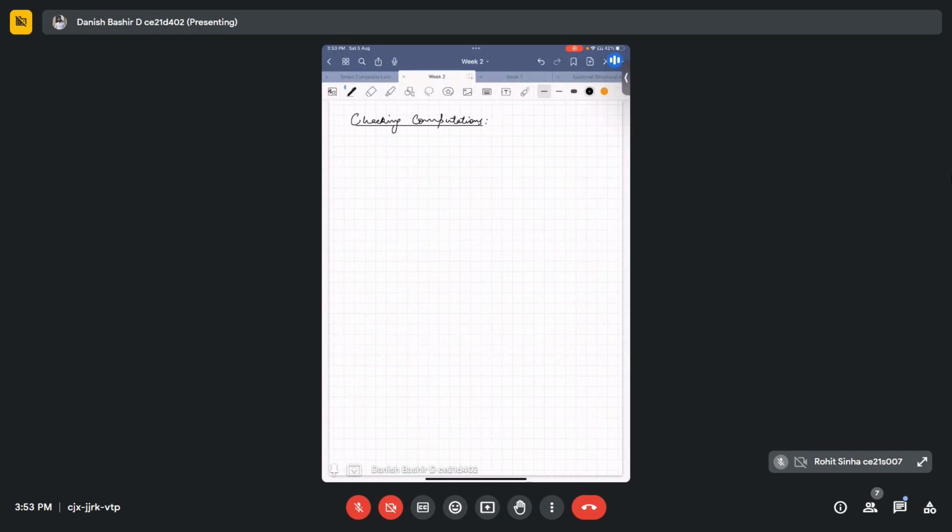If we take RA as positive, the summation of moments at point C is equal to... let's see. First we will calculate, then we will see whether it is equal to zero or not, because it should be equal to zero as per the moment equilibrium equation. So MC, first it will be minus 4 by 5 of RA, and it is at 25 meters lever arm. Then the 12 kilonewton is creating a clockwise moment, so 12 sine 60, with a 15 meter lever arm.